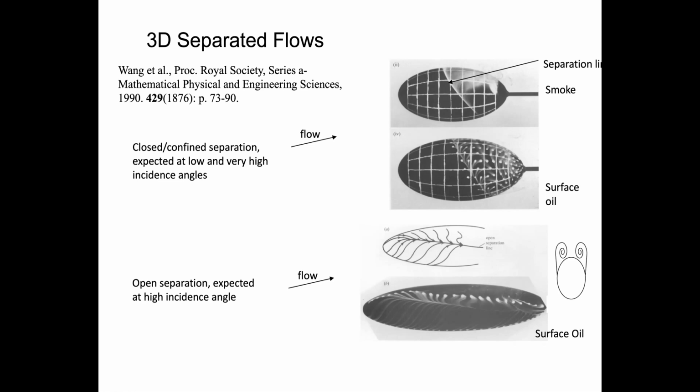But anyway, everything I'm showing you right now is what occurs at low Reynolds number flows. I don't think we have the slightest idea what we're going to see at high Reynolds numbers. But this is, if you want, the basic flow features that we are supposed to investigate. And in relationship to what Dave mentioned before, and I'll show you the setup, we tried to get the PIV system as close as possible to the leading edge because we really want to see the boundary layer just as the two stream surfaces meet each other. And that will affect the place where the flow detaches from the surface.